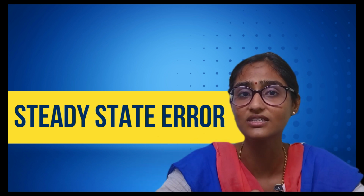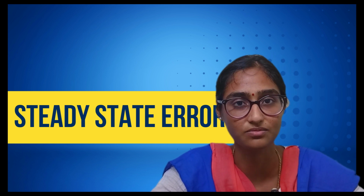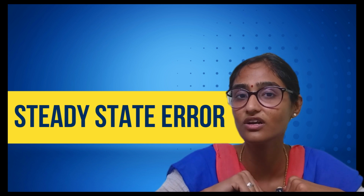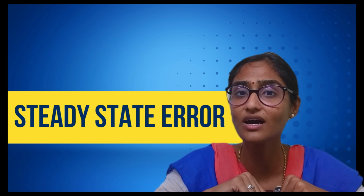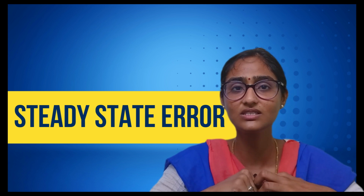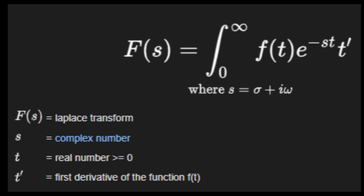Another point is the steady state error concept. It uses Laplace transforms. We are finding E of t and finding E of s in order to find the steady state error ESS in a static error coefficient. So what happens? This is valid only for stable systems. When the system is unstable, the Laplace transform isn't valid because Laplace itself has an e power minus s t term in it, which requires stability. Only for stable systems this is valid.